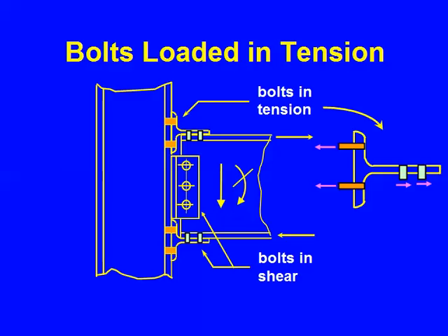So when we do that, then we can proceed, let's say, up to the top to find out what the forces are in the bolts that are sitting up there, including the ones that are in tension, which are the ones that I wanted to deal with, those bolts in tension. There's the free body diagram. A little bit of work will elicit the information that the shear in those bolts, there's a little eccentricity there, isn't there? But that's negligible, and it can safely be ignored. And then that gives me the force, the tension force in those 4 bolts, 2 here and 2 on the backside.